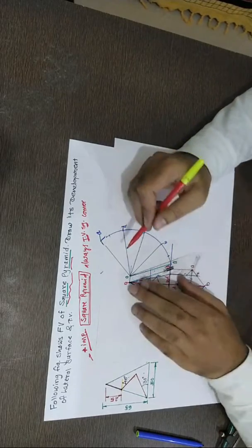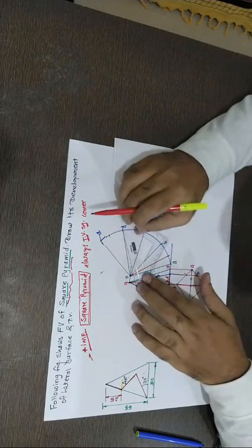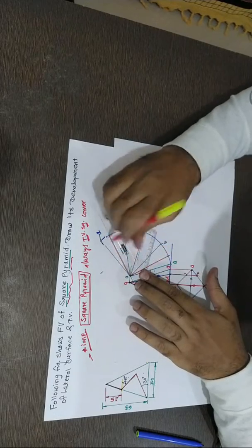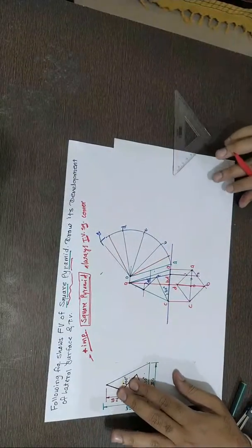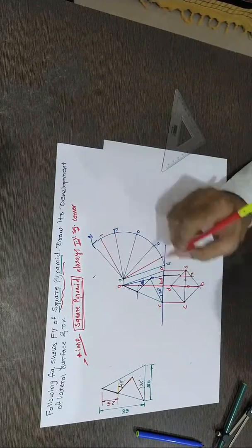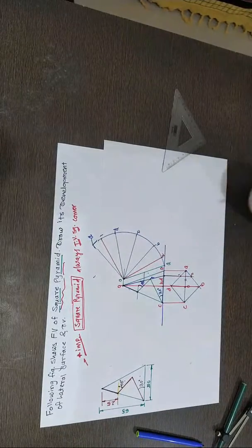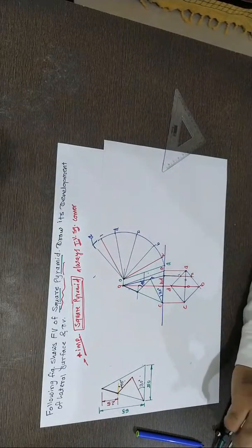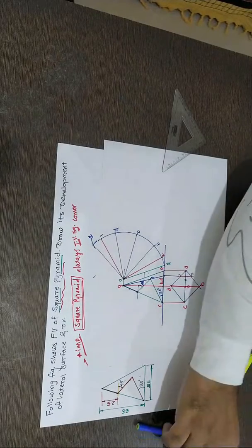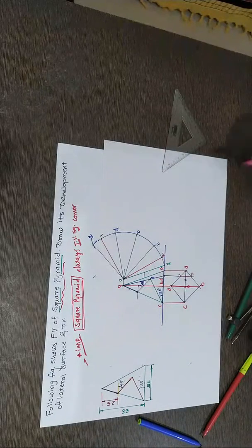So now join those edges, which I have already joined in the front view of the question. Yeah, thank God this lies on the page. Okay, fine. Now I got this is for 1, AD for 1, AB for 2. Use any notation, no issues. So now project those points onto the true length of A.